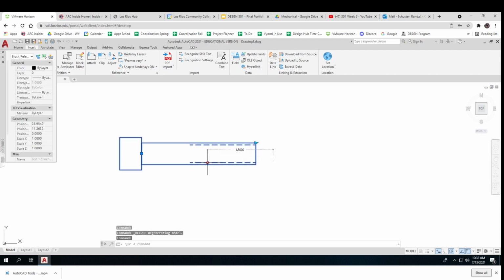So now, how do you do thread pitch? Well, that's normally an attribute because you're calling it out as an attribute, and then you don't normally model that, because it's just a feed rate on your machine, and what's really modeled is your thread form, right? You just call out a thread form and a pitch, right? I see.